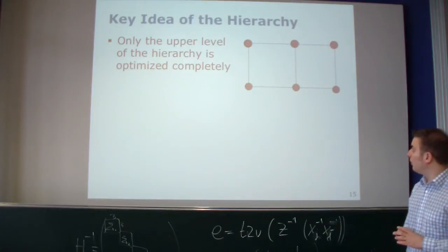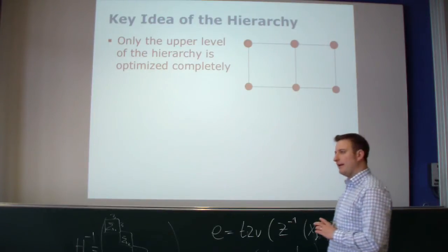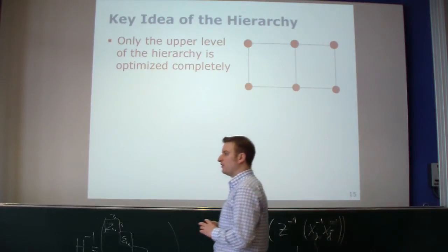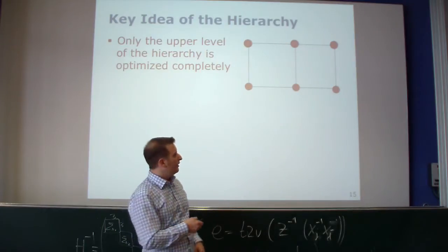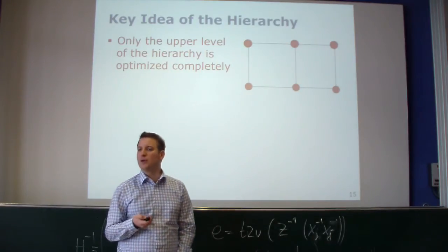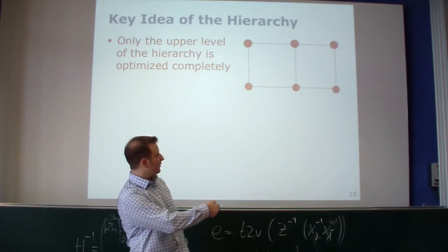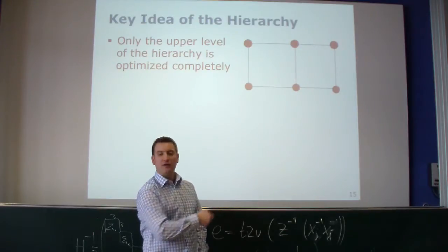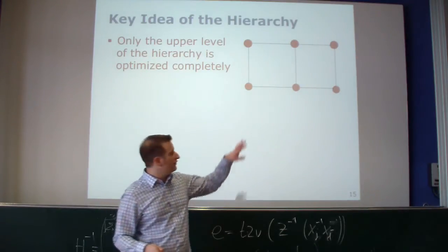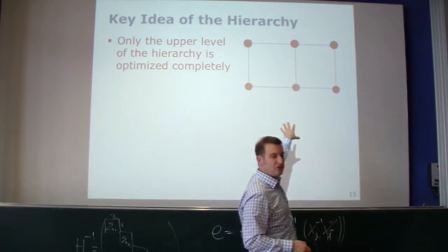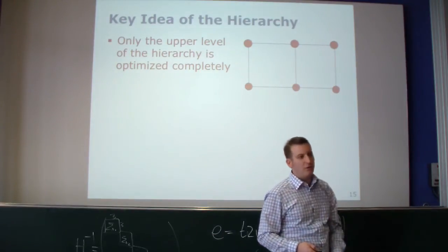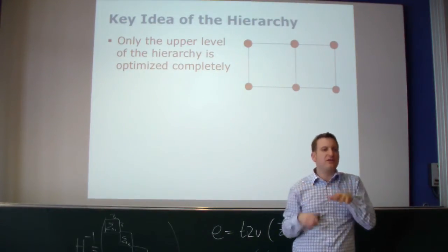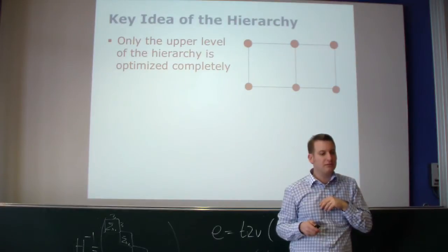Okay, so let's say it this way. Typically, the robot wants to know its local surrounding quite accurately. Let's suppose the robot is here, somewhere in that local area of that node. So then it may propagate this information downwards here in the center. It goes one level below. It does the rigid body transformation of the nodes down there.